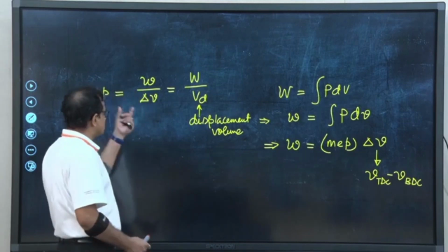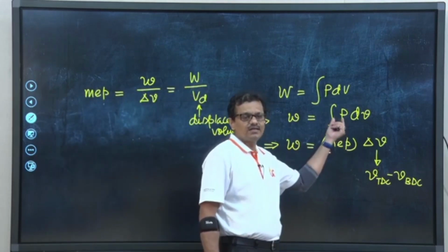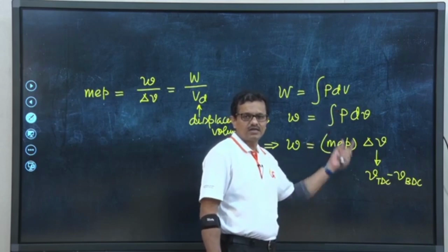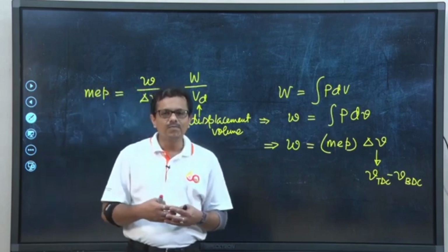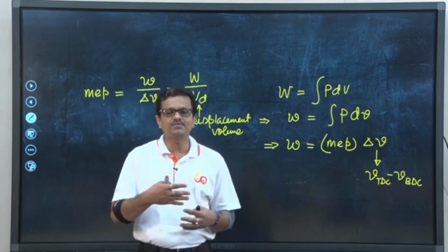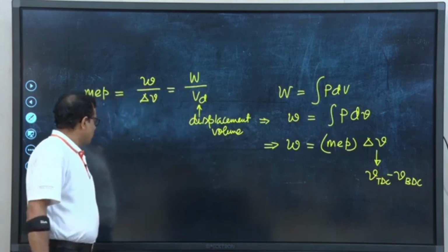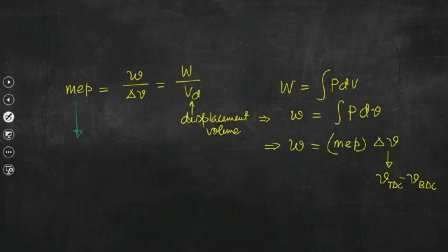So, mean effective pressure is not only the concept that we are writing here only to eliminate the spatiotemporal change in pressure that is there always inside the cylinder, to get rid of that issue, but also this parameter is an important parameter for comparing the performance of the engine as well as for comparing the design of the engine instead of torque and power. So, also we had discussed that we could write this mean effective pressure in its different form. So, mean effective pressure, we are including B as the suffix, we are writing B.